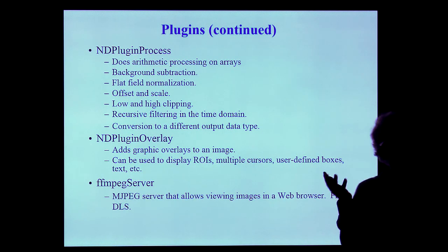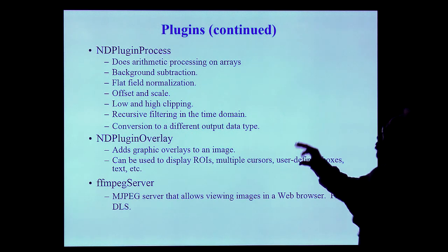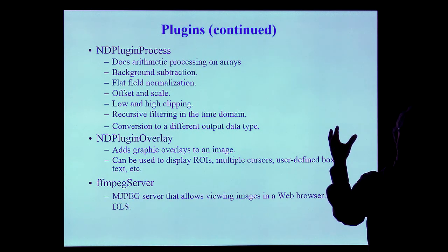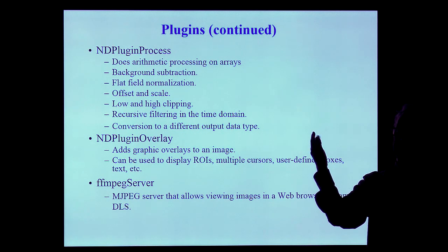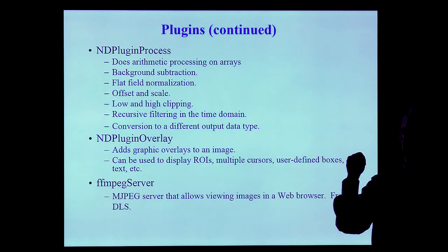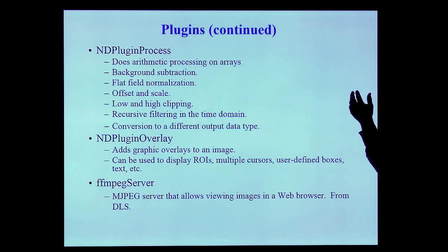So the question was, there's only 4 regions of interest. The number and which plugins are loaded in your IOC is just determined by this little script called commonplugins.cmd, right? And that loads 4 region of interest plugins. But there's nothing to prevent you from loading more region of interest plugins, or fewer. And similarly, it has 5 statistics plugins.